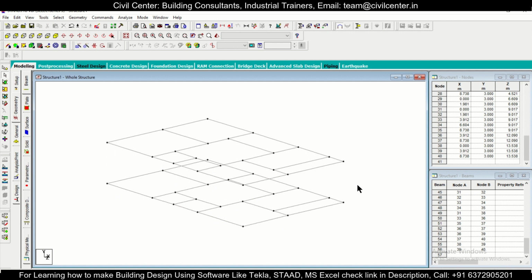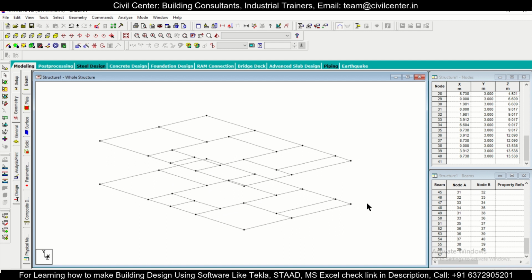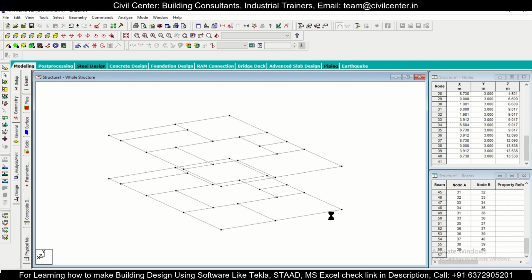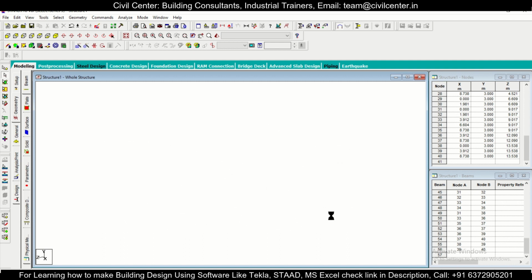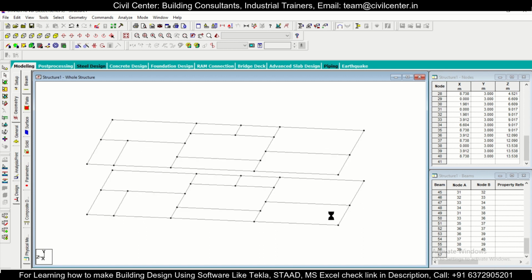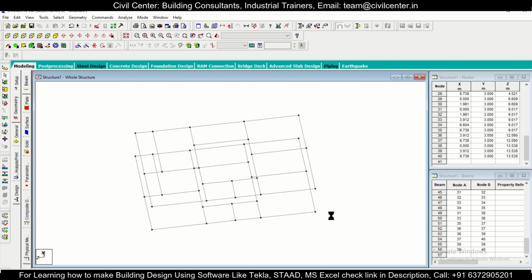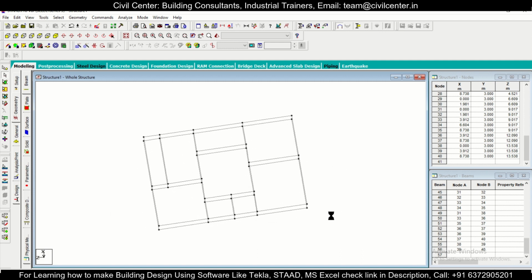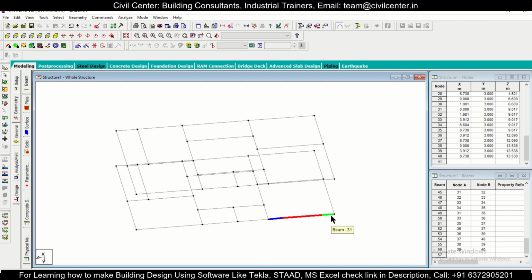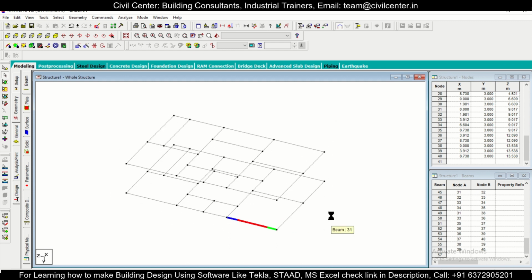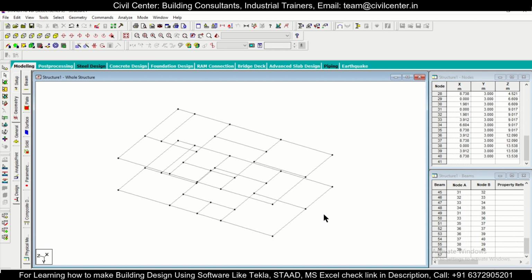Now we'll connect our columns. While connecting columns, please ensure that you have the beam column plan with you, because we'll assign the positions of our columns accordingly. Now if you view it from here, you can check this from here. If we rotate this model, we can suitably place the columns.